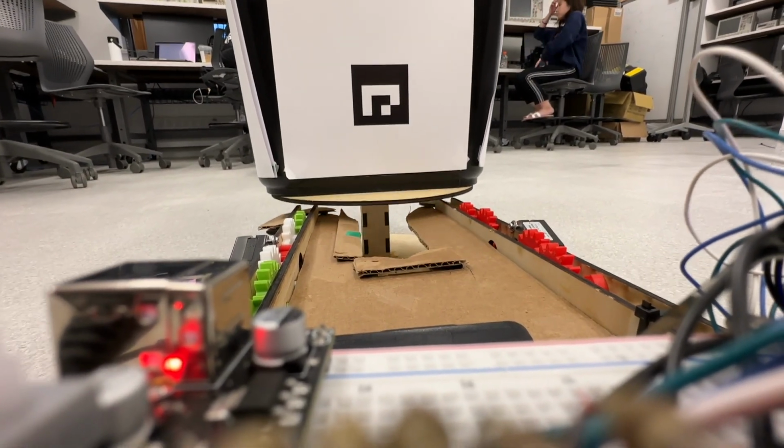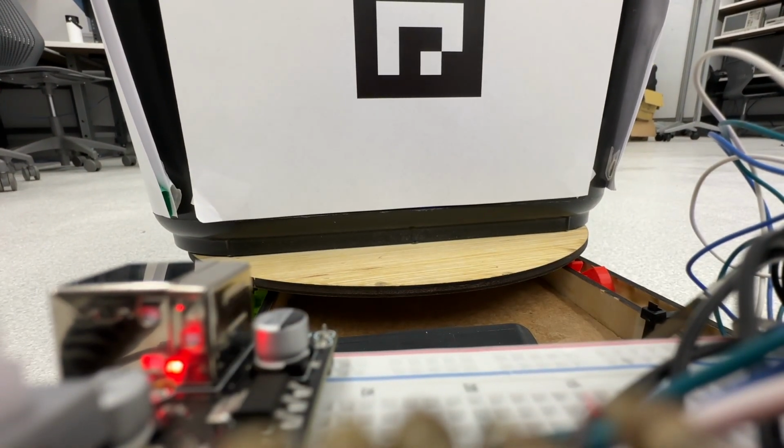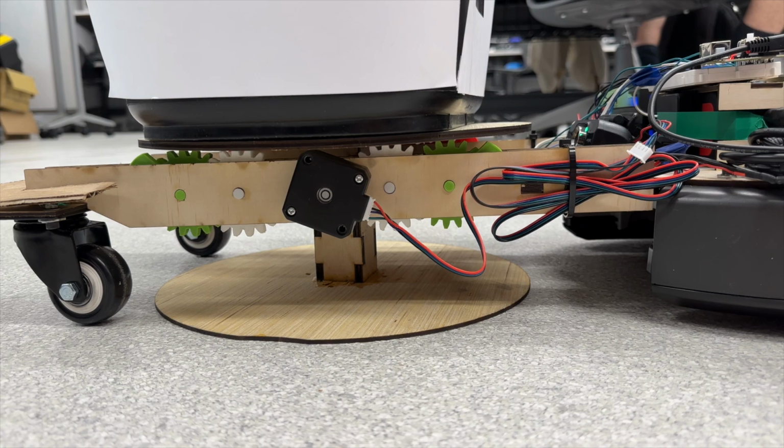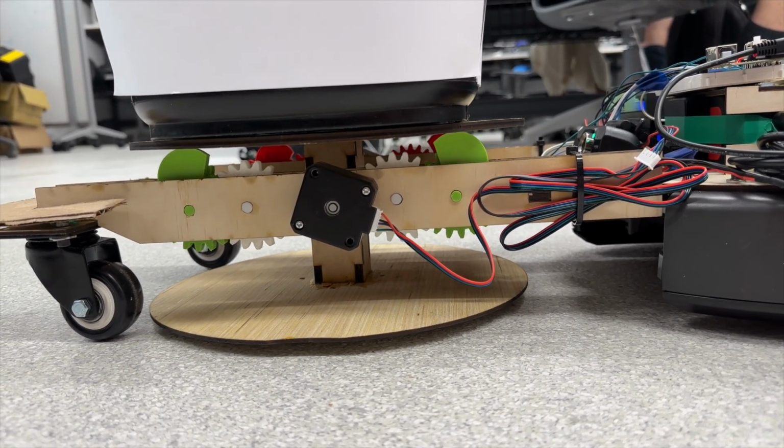The alignment funnel between the arms ensures that small errors in the vision or location navigation systems don't impact our ability to move the lift arms under the trash bin. Once the arms have been aligned under the trash bin's base, the state coordinator commands our stepper motors to lift the bin. The motors precisely drive a gear system that increases the effective torque output, allowing us to lift heavier